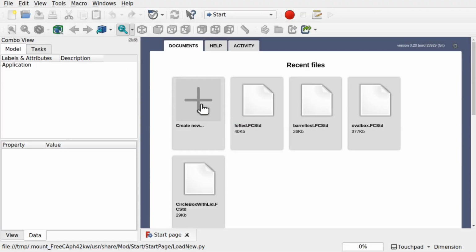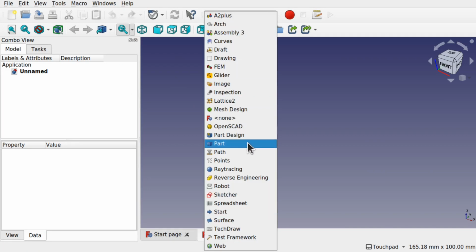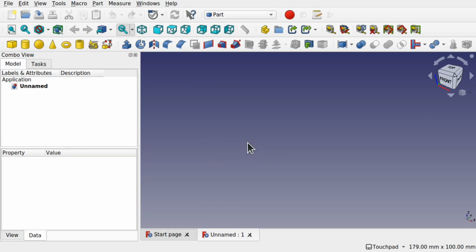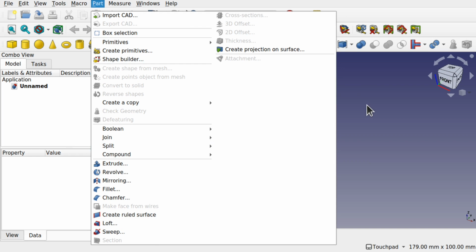For this video, we're in FreeCAD and we can create a new document. And we're going to be using the Part workbench for this one, because I want the model to be made of separate sections. So we're looking at multiple bodies in there, which Part Design at this time doesn't support. The reason why I want to use multiple bodies is to add more shape and texture to the barrel that we're modeling. So in the Part workbench, we're going to be using the Part Loft to loft through sections of that barrel, and we're also going to be using the Boolean operations.